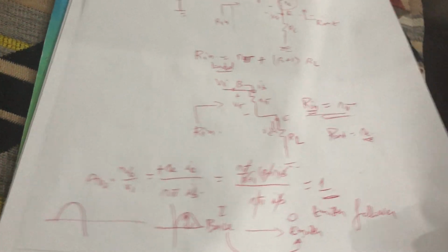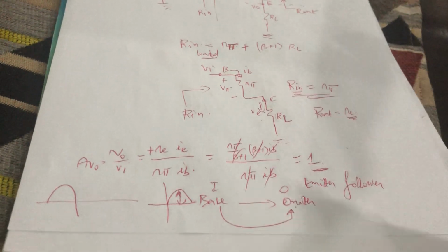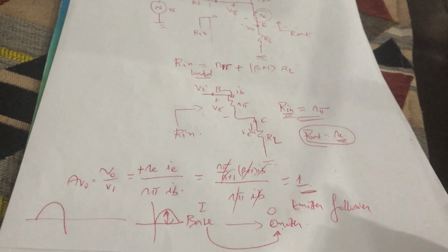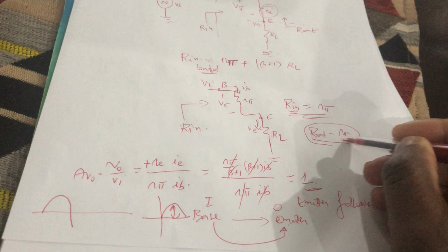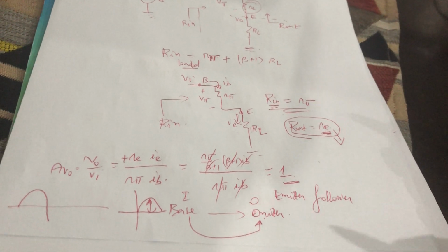But why would you need an amplifier with a gain of 1? That has been answered already. I think the aim of designing this common collector amplifier is to tap into its guaranteed low output impedance, which is a good characteristic of an amplifier.